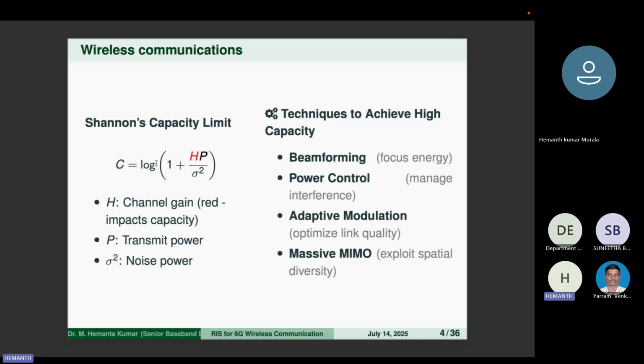But one of the drawbacks is that the more antennas you use, the more RF chains are required, so more power consumption is required. In 6G the main target is energy efficiency, so low power must be used in 6G. So this is also not working. Massive MIMO has another problem too: self-interference is formed, antenna to antenna.